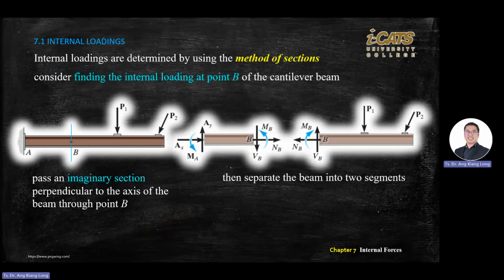That is my method. I always assume forces going up are positive, going to the right positive, anti-clockwise positive. Solve for A first. Not solve, but at least you label it. There are forces at A. Now, if the question asks you to find internal forces at B, you break the component into two parts and redraw the component, like what you see on the screen here. So you break at point B, into two parts, on the left and on the right.